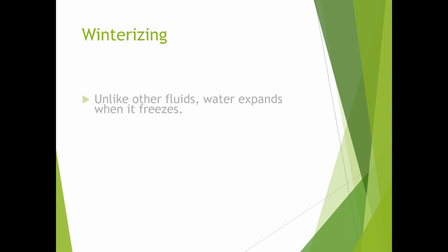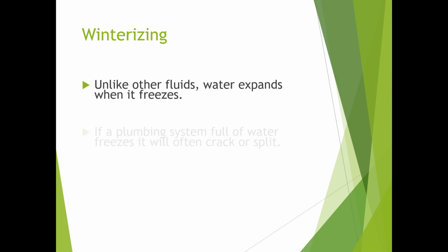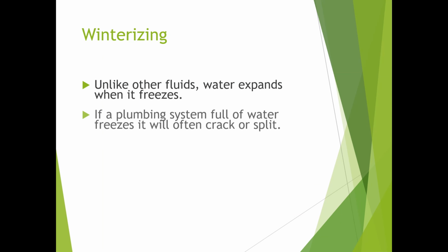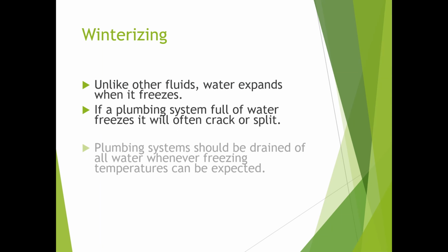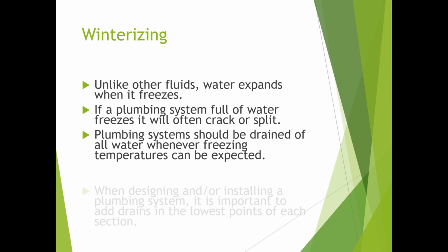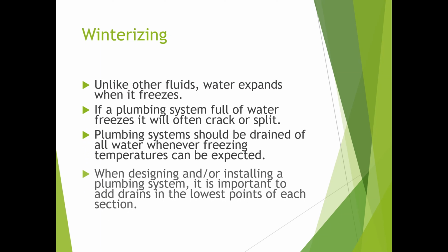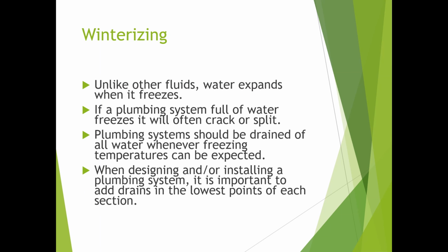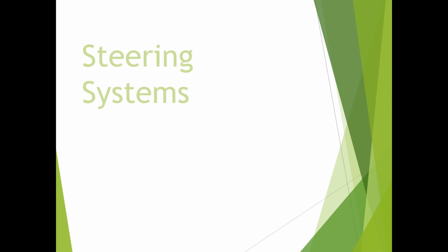Winterizing. Unlike other fluids, water expands when it freezes. If a plumbing system full of water freezes, it will often crack or split. Plumbing systems should be drained of all water whenever freezing temperatures can be expected. When designing and/or installing a plumbing system, it is important to add drains in the lowest points of each section.